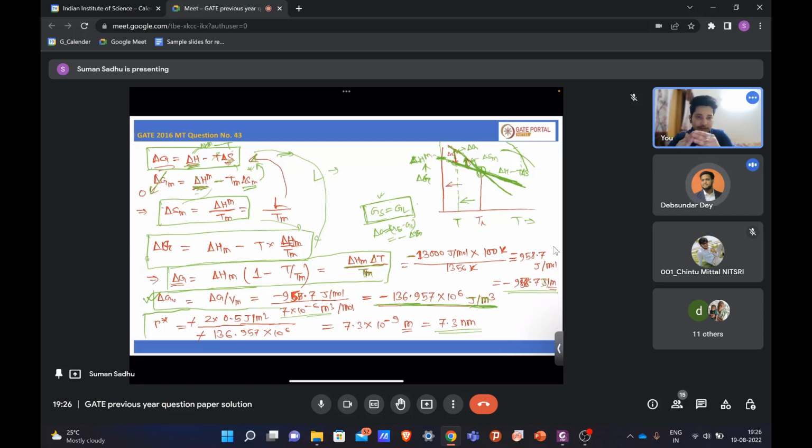And that delta T also depends on what type of nucleation is occurring, either homogeneous or heterogeneous. For heterogeneous nucleation, you have extra surface, like from the inclusion you can get one surface, from the mold wall you will get surface. Since you are already getting a surface for the nucleation, the energy requirement will be less, right?